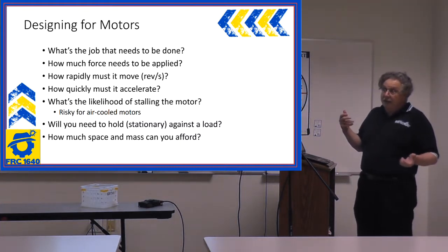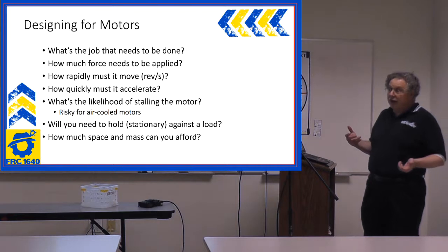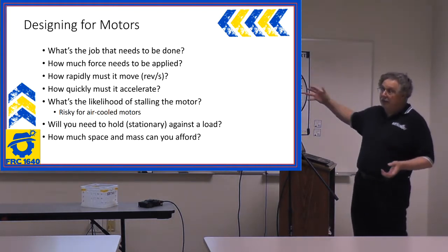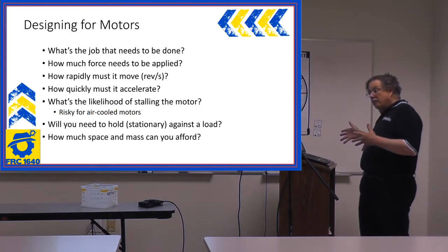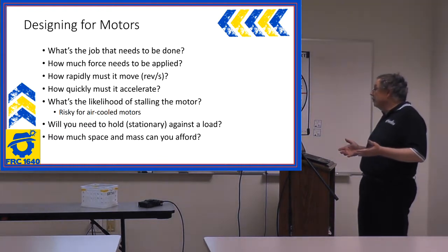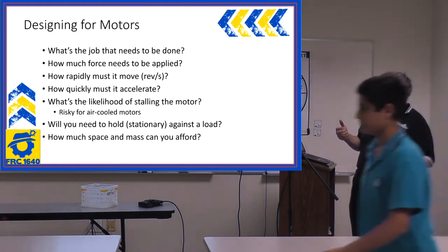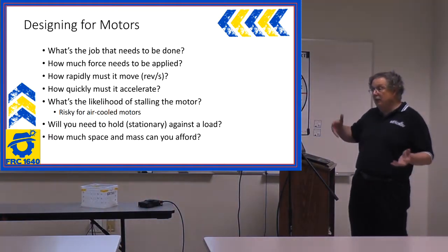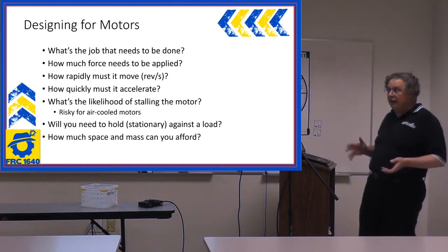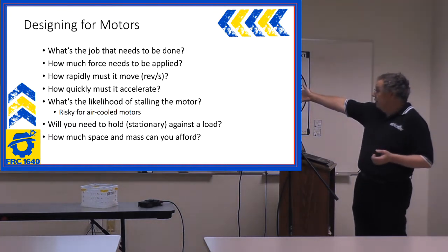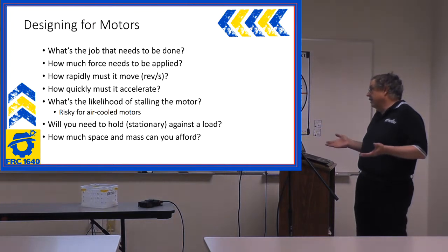If it's used for your drivetrain, ultimately that's going to determine what speed your robot's going to move. How quickly does it need to accelerate? Do I need to go from 0 to 10 feet per second in 1 second? I don't know, but you need to know because you're designing the robot.